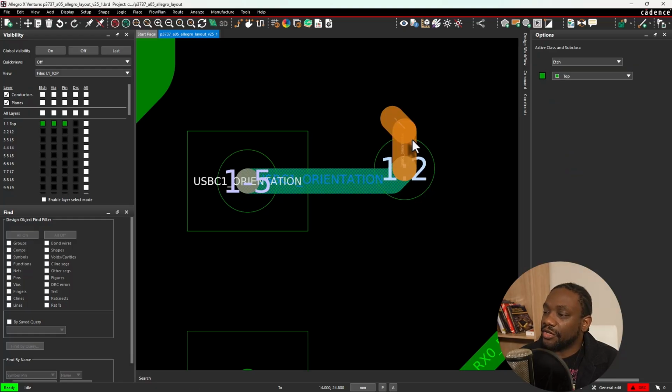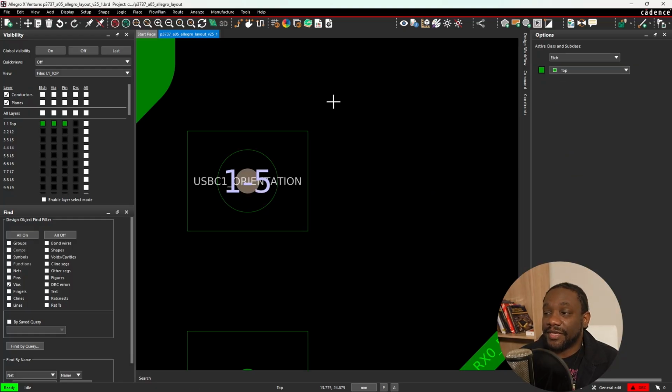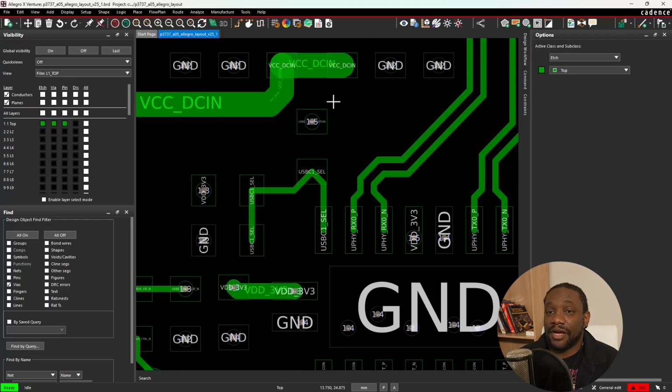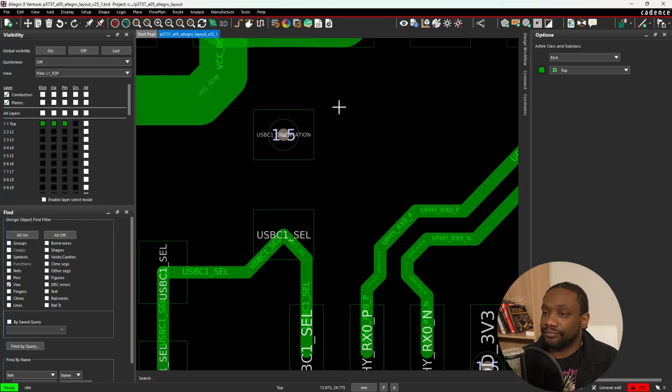Okay. This is how you can maximize your spacing during your routing for HDI applications and also manage your signal propagation. But yeah, very common practice in HDI PCB design. All right, that's it. You've learned the primary reason why we use microvias, blind and buried vias in HDI PCB design.